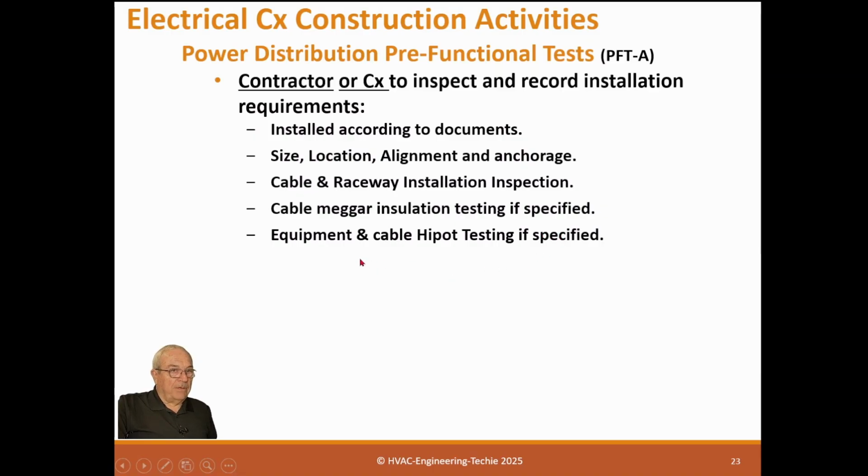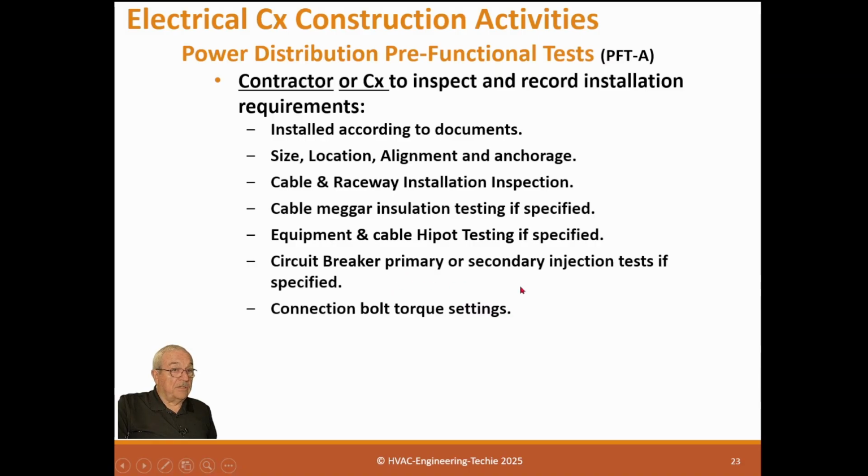Equipment and cable high pot testing, if specified. Circuit breaker primary or secondary injection test, if specified, has been done. Connected bolt torque settings have been done and verified. And then a verification record form, to put everything on a record form.